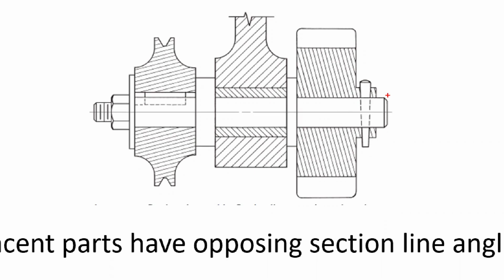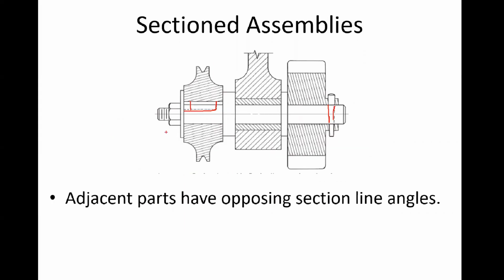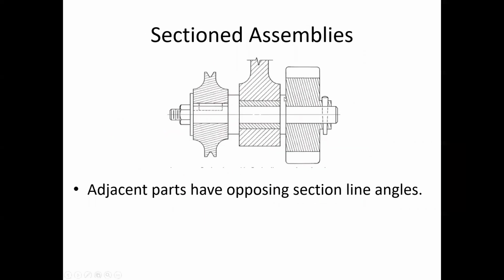They're either going to have to be hidden lines or solid lines. I mean, you would see that if you were cutting it right down the center, you'd actually see edges, same way here. So I don't know. There are hidden lines in there. That might be one of those cases where I'd make a special note if I were asking you to do something like this.